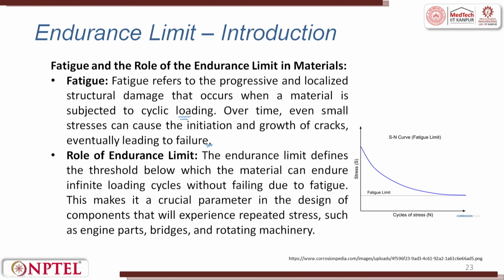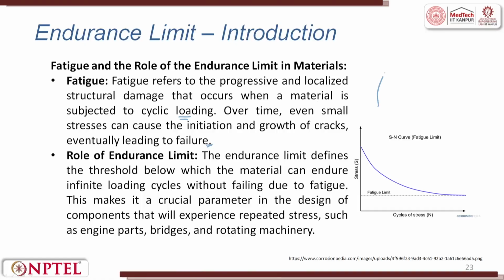Right. So, fatigue is when you take a component and keep bending this component multiple times, cyclic load up, cyclic load down. So, tensile, compression, it keeps on going. So, at one point of time, at the place wherever I bend, you can have a crack forming. So, that is the localized structural damage that occurs when it is cyclically loaded. Over a time, even a small crack starts growing. Once it starts growing, there will be many more cracks joining, or the energy which is here is very high. So, that keeps pushing it further, progressing.